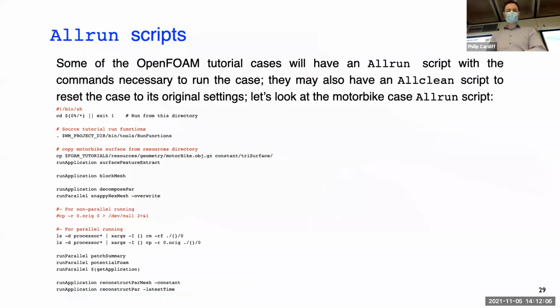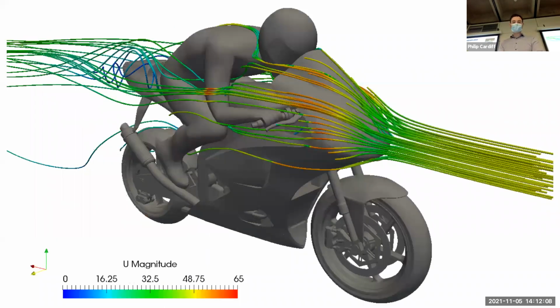Yeah, so this is taken from online. This case is set up and included in OpenFOAM as an example for the simpleFoam solver and snappyHexMesh. This CAD is available, and I imagine it took a while to make, but the individual patches are defined in the CAD, like helmet or arms or whatever. So you could specify different mesh settings on each of those and calculate the drag on each individual part.